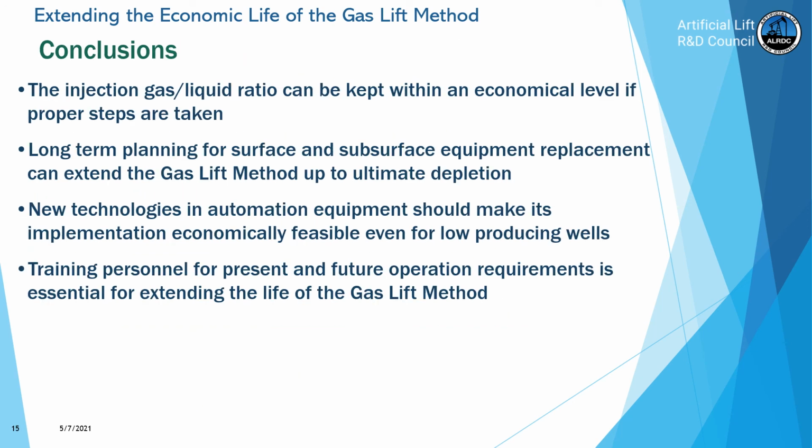Well, finally, we can conclude that yes, the injection gas liquid ratio can be kept within an economical level if the proper steps are taken. Long-term planning for surface and subsurface equipment replacement can extend the gas lift method up to ultimate depletion. New technologies in automation equipment should make its implementation economically feasible, even and especially for low producing wells. And also keep in mind that training is one of the most important things.